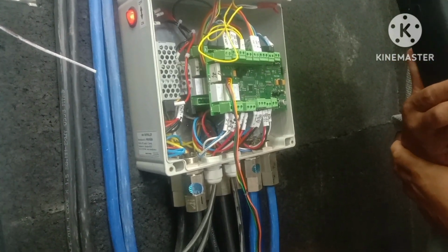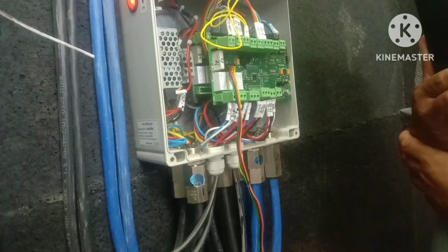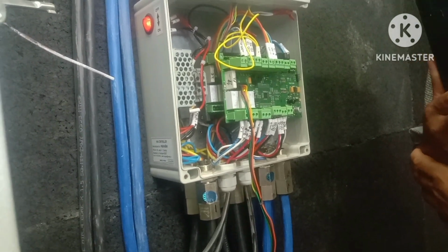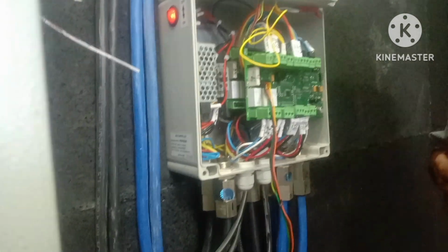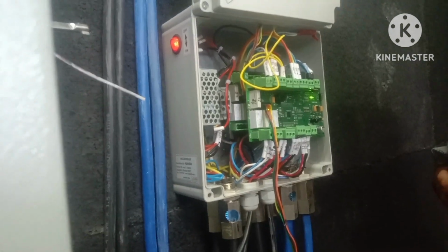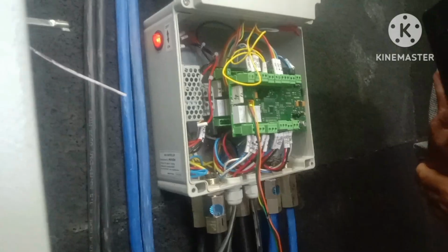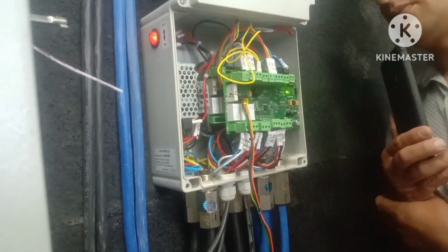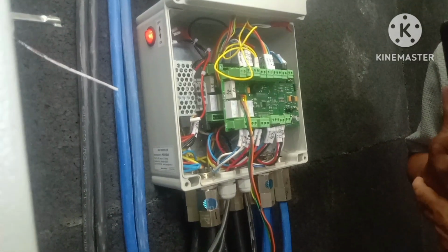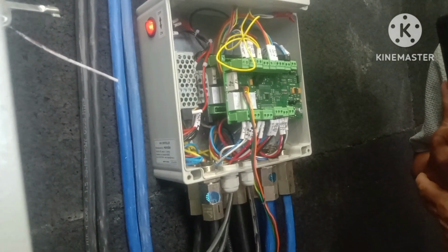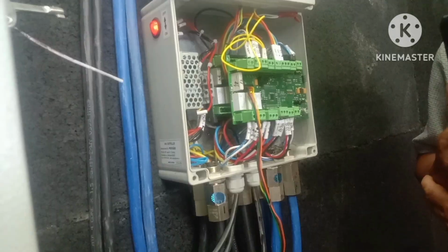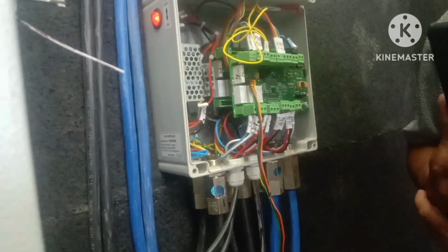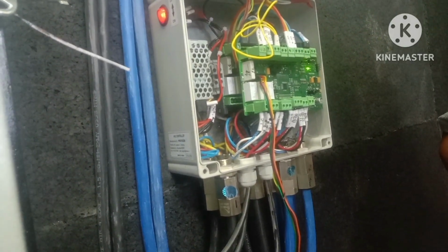While doing that we should make sure that the power supply is off, so the controller should first be in the off condition. Then we will connect the same wires, which were connected to the previous or faulty controller, to the new controller. After connecting all the wires to the new controller, we will turn it on and test whether we are now getting feedback or not.